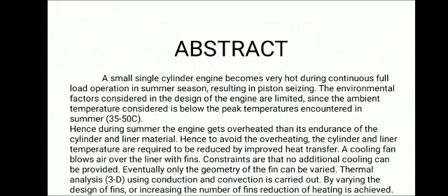Abstract: a small single cylinder engine becomes very hot during continuous full load operation in summer season, resulting in piston seizing. The environmental factors considered in the design of the engine are limited, since the ambient temperature considered is below the peak temperature encountered in the summer. Hence, during summer, the engine gets overheated beyond the endurance of the cylinder and liner material. Hence, to avoid the overheating, the cylinder and liner temperature are required to be reduced by improved heat transfer.